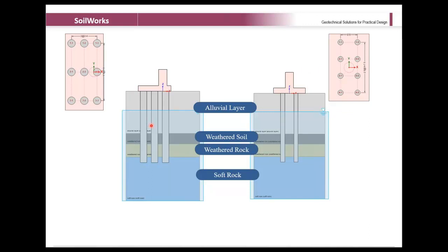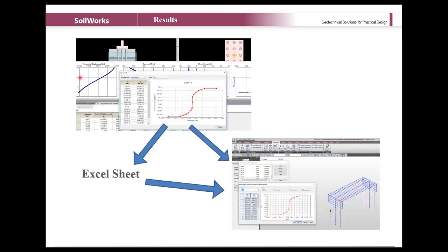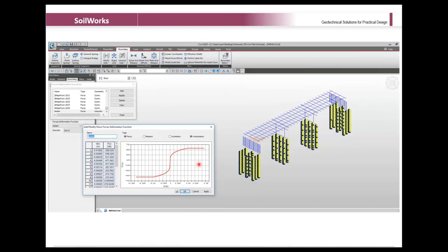So basically, you have modeled the complete model using Midas SOILWorks, and you got nonlinear springs that can be taken to Excel, or else you can directly copy and paste them into your Midas Civil software as well. Whenever you post the complete data, these are all the nonlinear springs that will get developed.